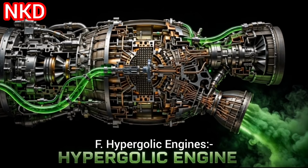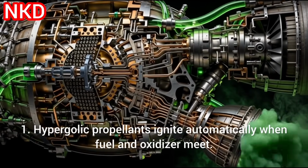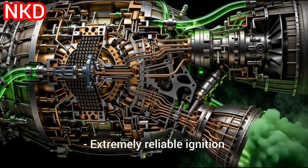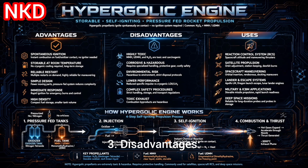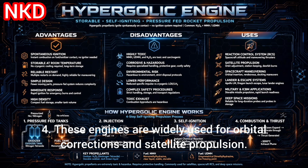F. Hypergolic engines. 1. Hypergolic propellants ignite automatically when fuel and oxidizer meet. 2. Advantages: extremely reliable ignition, multiple restarts, excellent for spacecraft maneuvers. 3. Disadvantages: highly toxic, expensive handling procedures. 4. These engines are widely used for orbital corrections and satellite propulsion.